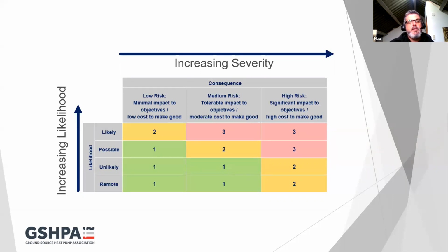So the risk is obviously strongly client influenced, and also, of course, it's site influenced. Do we need an expensive numerical model on a small open loop system that has well-balanced thermal loads, heating and cooling about the same, in a major aquifer that's very remote to any potentially temperature sensitive receptor? Well, no, probably not, because the risk there is small. It's down here in the bottom left-hand corner. Low likelihood and low impact.